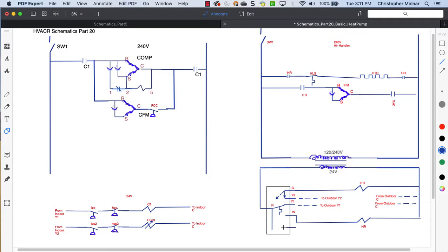So we're going to put an extra terminal in, and then I'm going to basically put a switch in. It's a single pole switch. And let's go ahead and mark this designation on the output of this thermostat. We're going to label it O. Heat pump thermostats will most often have an O terminal. Sometimes the older ones may have had a B terminal as well, but most of your newer ones are going to be an O terminal.